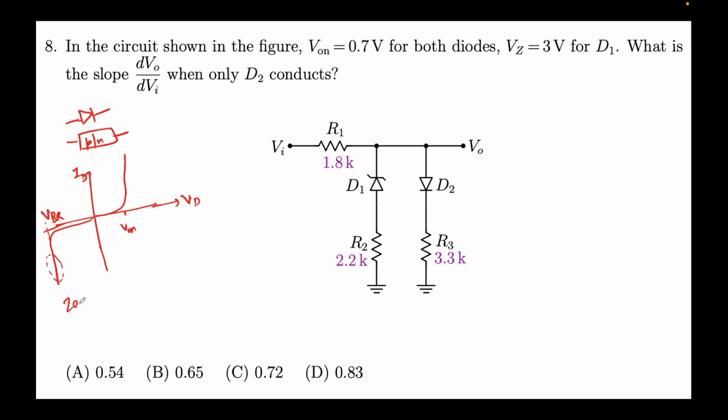Those diodes are called Zener diodes, and they're represented by this symbol, Zener diodes, right? So if we reverse bias them beyond their breakdown, they will support large amounts of current. And in forward bias, they'll obviously behave like a normal diode. So this is the good point about Zener diodes. Hence they are also used in voltage regulation. That is one of their primary applications, voltage regulation, right?